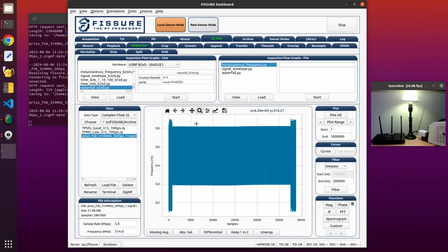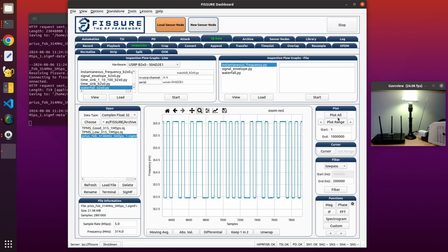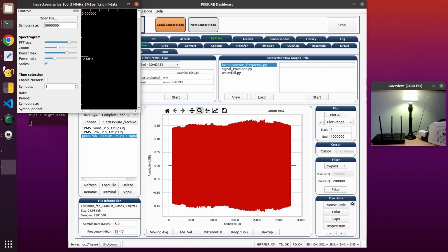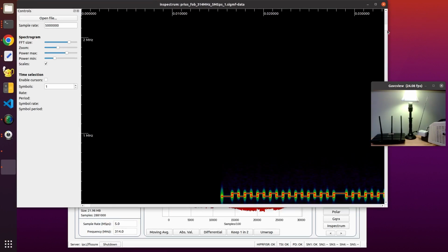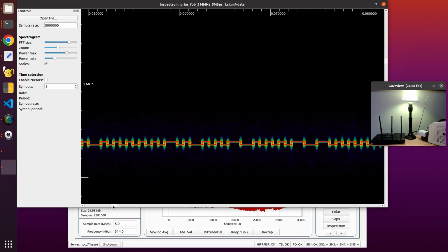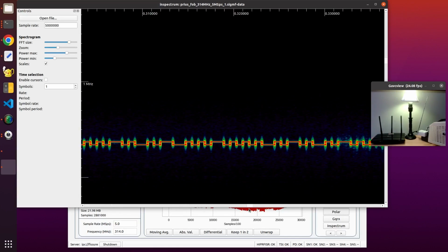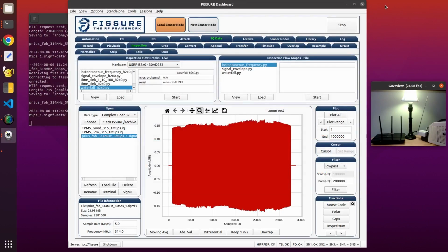We have these analysis buttons down here. So you get ones and zeros for FSK. You can load up the signals in other tools. So like if I want to view this in Spectrum, it will copy the SigMF information down here for frequency and sample rate, and it's used to launch this program from the command line. And if I scroll down here, you got the ones and zeros, and it looks kind of nice. So if something like Universal Radio Hacker had a command line option, I could just click a button and open it up and get the ones and zeros pretty quick. But if it doesn't, I don't know how to do it. So make sure people have command line options for opening IQ files. That would help me out.